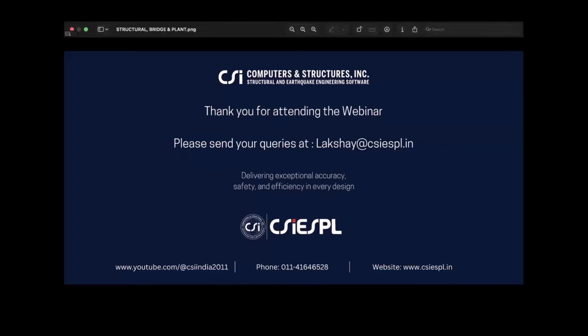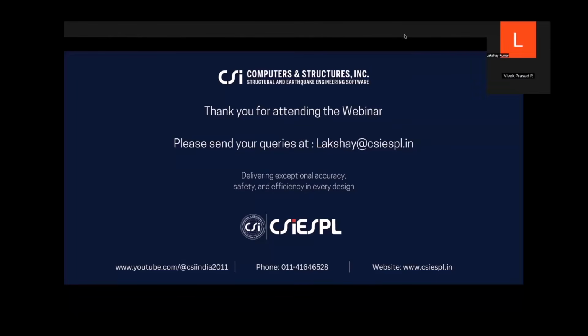If it is very close, then correction factors will be applied, and when they are well separated, it will be SRSS automatically. Because the computational effort is not needed by the user, the program is taking care of it, so you can go with the CQC for the modal combination. SRSS directional combination is required only when you're combining more than one load in the load case.